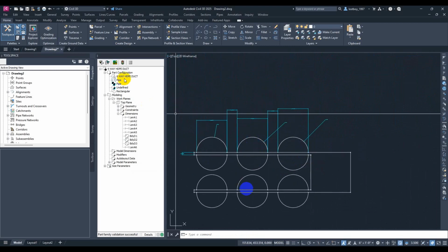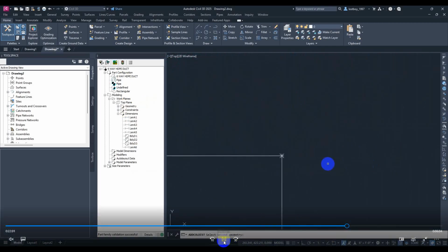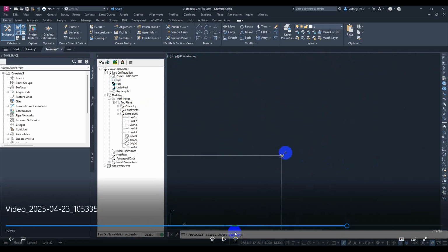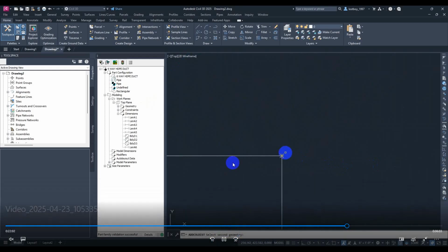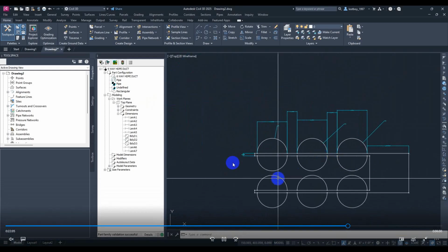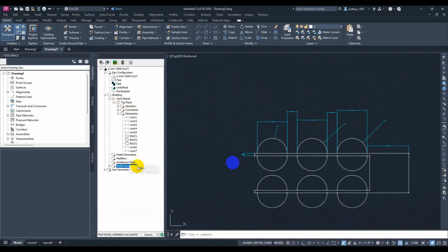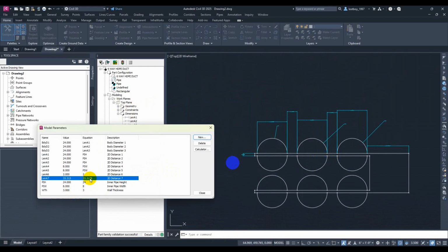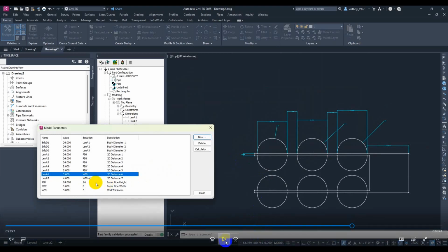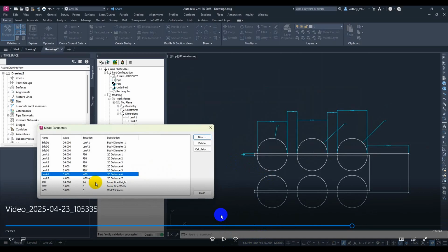Yes, now they have the same value. This part also I have to be tying it, somehow I have to make this connection. So I will add a dimension, and identify it later by parameter, as you will see. Wall thickness, and this one I will make it wall thickness plus any value. I can make 1 millimeter, or smaller than 1 millimeter, because I have to make this vertical line just be parallel and very adjacent to, or very close to, this vertical line.